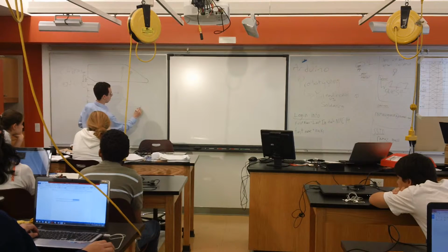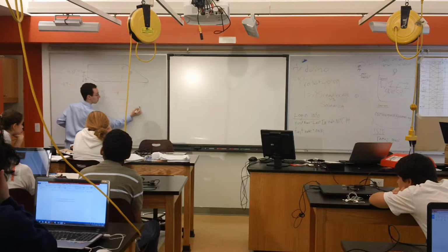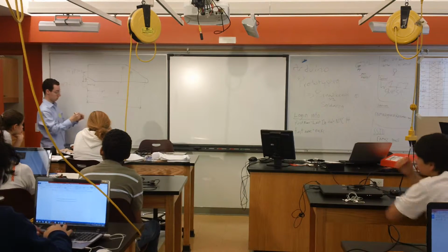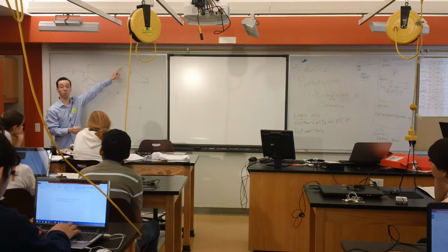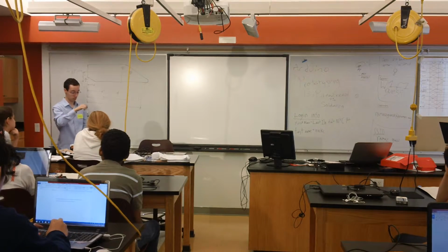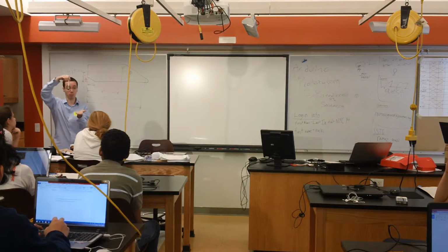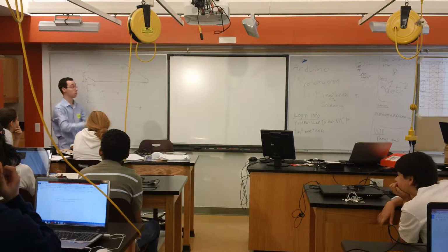Okay, so this is. If you haven't noticed by now, when you draw dimensions to a circle, you draw the dimensions not to the edge of the circle, but to the center of it, which makes it a lot easier for your machinist, because they're moving a drill bit, for example. They're going to put the drill bit right over where the hole's going to go, then drill down and through.